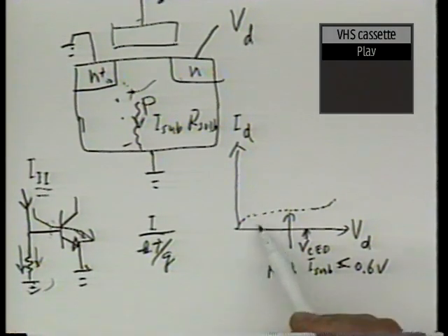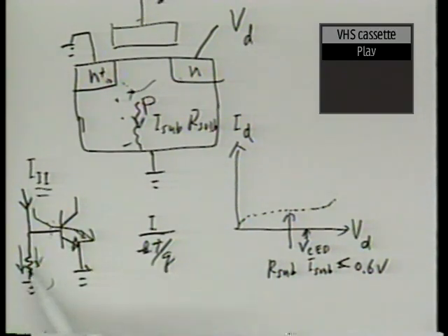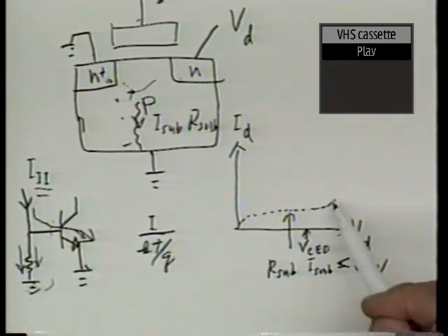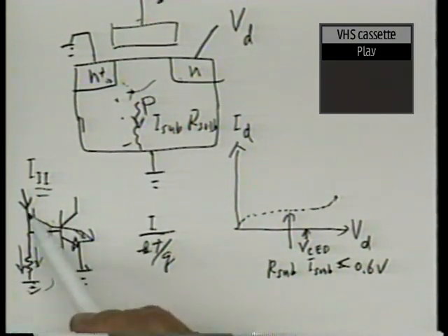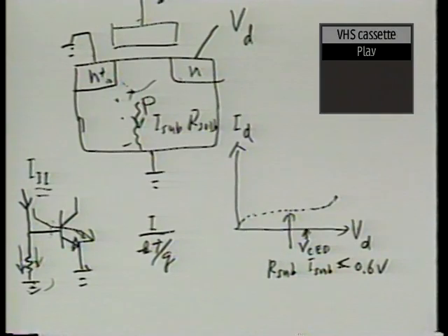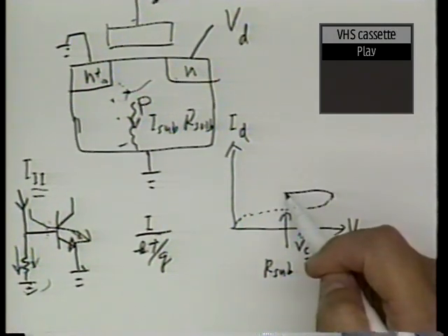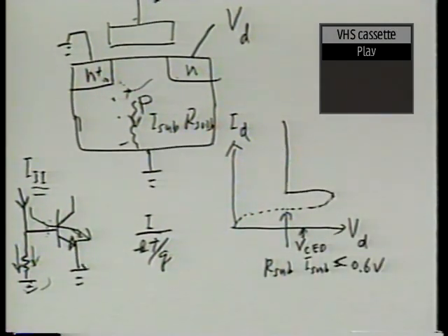So we can pass through that no problem, because at this point the impact ionization current is flowing through this. At this point, however, the junction is forward biased. Now the PN junction becomes the favored path for any impact ionization current. So your feedback gain starts to increase, and you suddenly just drop back to this. This is called a snapback, right? So this is the theory for the bipolar transistor breakdown voltage. Okay, other questions?